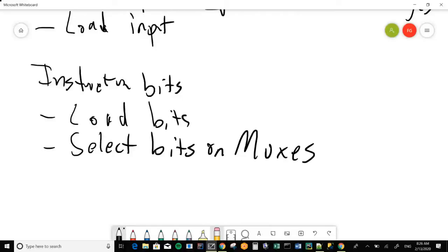Typically, the bits in the machine language instruction can be directly routed, or sometimes mediated by a little more logic, into the select input for a multiplexer that controls what might be coming in. That, too, is an essential aspect of instruction decoding. What are you going to change? What load bits go high? What thing goes into the thing that's changing? Select bits on a multiplexer. That all makes sense so far?